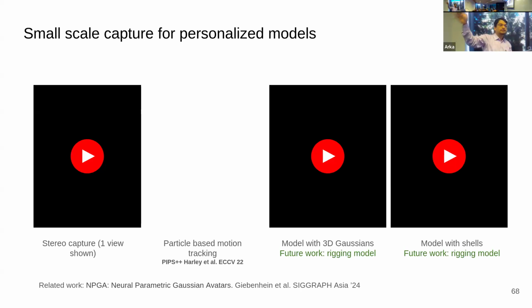To increase the performance of my rig, the first modification that I would do, if I have to keep the form factor intact, is I would switch to high resolution cameras, and maybe that is why I said the iPhone may be an attractive choice, because it is really good if I have a co-located low resolution metric depth sensor with a high resolution monocular image. That way I can offload the meat of the depth calculation to the monocular network, and then I can take parts of the scene and upgrade them to metric, so that registration and all those things are immediately better.